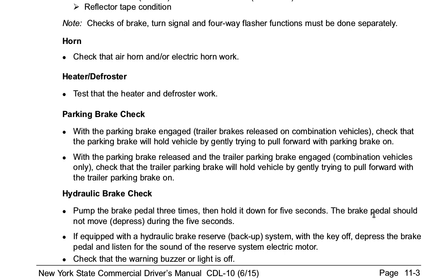With the parking brake released and the trailer parking brake engaged, combination vehicles only, check that the trailer parking brake will hold the vehicle by gently trying to pull forward with the trailer parking brake on. Hydraulic brake check.